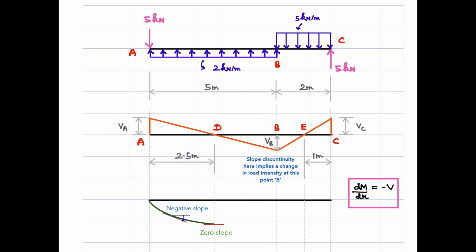So if we start with the span AD, we see that the ordinate is positive and maximum here and attains a zero value here, right? Then the slope of the moment diagram should be such that the slope is maximum and then becomes zero when it reaches D, but with a negative sign, right? Therefore, if the ordinate is positive here, then the trend of negative slope in the moment diagram should show that, right? So we see that for us, the clockwise slope is negative, right?